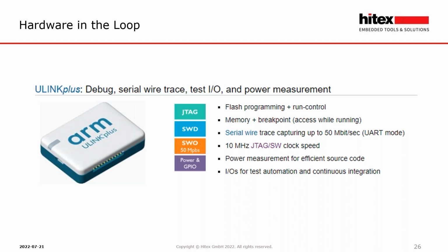Now, when we are testing on the hardware, we've got a choice of various debug adapters. But within the MDK, there's a debug adapter called the ULINK Plus. So this has a fast download time, but also it has a built-in logic analyzer that gives us dedicated digital and analog I/O channels. So this means within our test cases, we can generate hardware-in-the-loop testing.